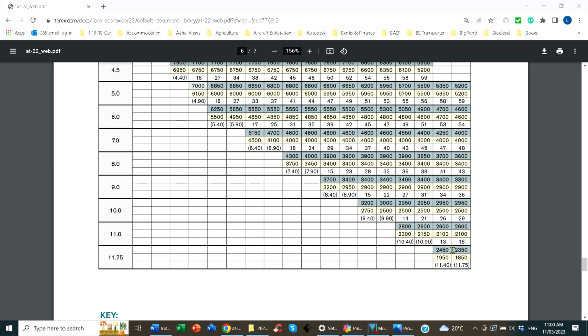The minute you steer the vehicle to move that load away, your rating has dropped, perhaps as much as 500 kilos. So you need to be very aware of this situation. It's difficult for operators in the heat of working to be able to remember all of these things.